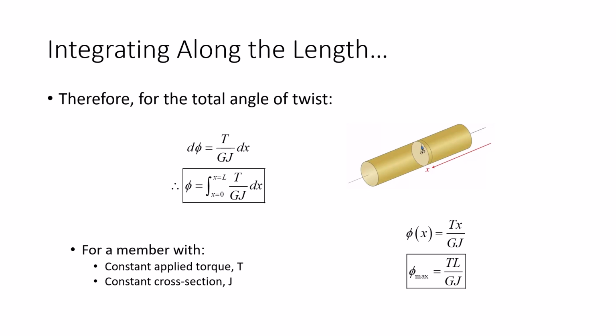So, let's take each of those four properties. What's on top? An applied load and the length. What's on the bottom? Material property, cross-sectional property. I'm going to break out the chalk. How did we determine the axial elongation of a bar? Applied load, length, material property, cross-sectional property. Start to see why we're doing torsion right after axial loads, because there is an analogy to the math that we do and to a lot of the problems that we solve as well.